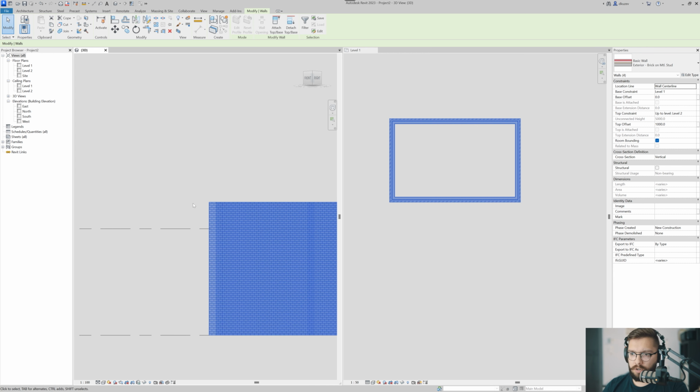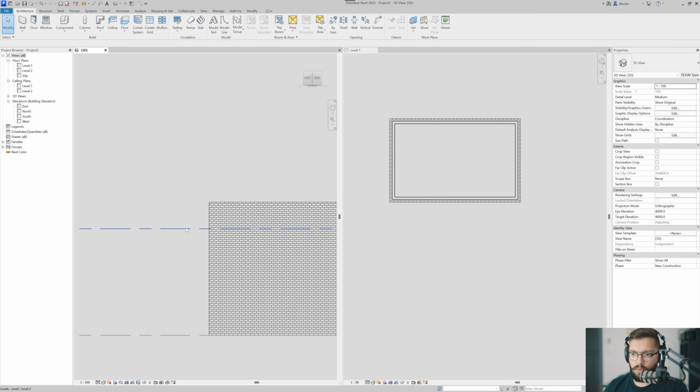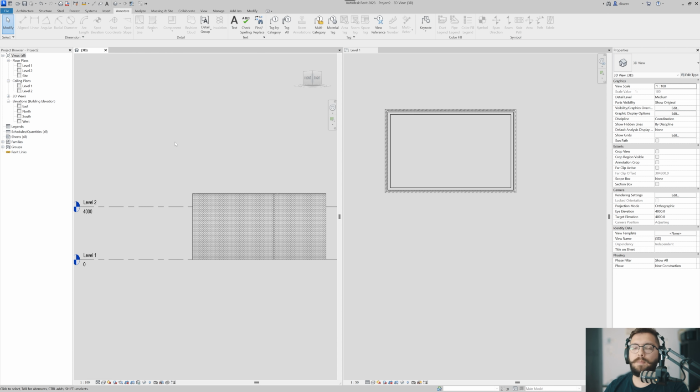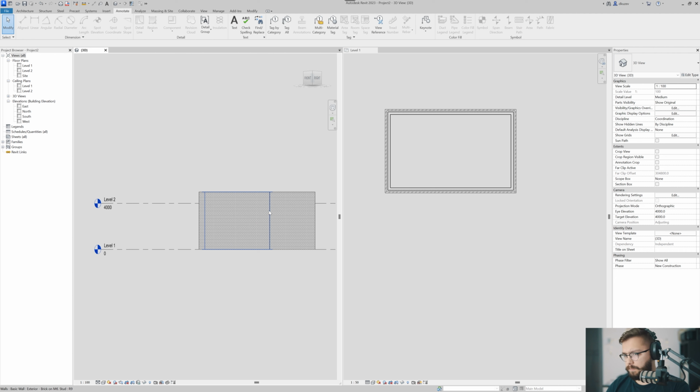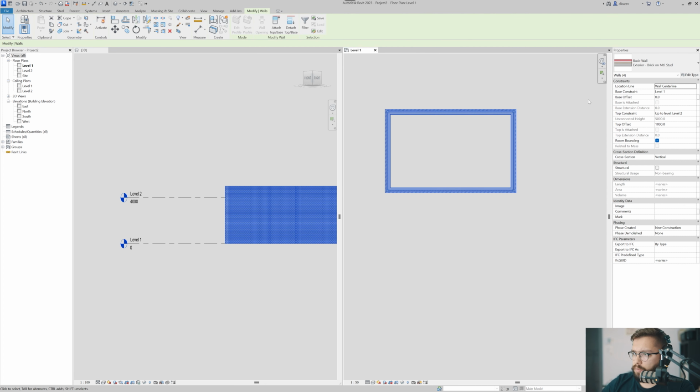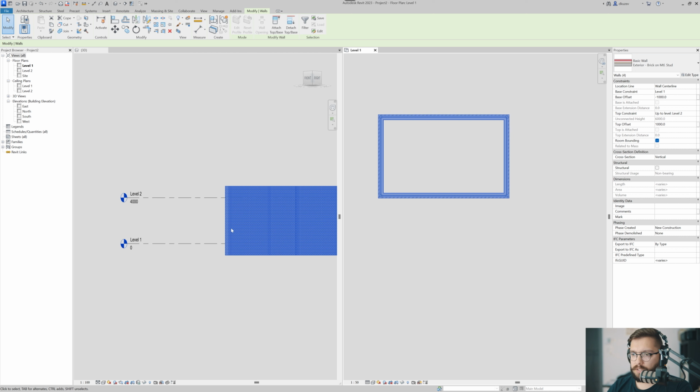And you would see that here I would have exactly 1 meter of what? Because I'm in 3D, obviously, never mind. But it surpasses it here by a meter. If I select my walls again, you will see that there's this thing called base offset. It's exactly the same thing as the top constraint. If I do 1000, you'll see it's going to lift it up. If I do negative 1000, it will bring it down.